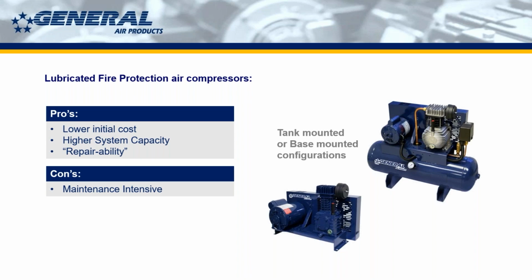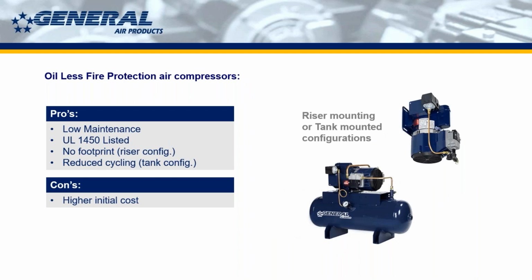And that's really the big difference. If somebody's trying to decide between oilless and lubricated, it's all about, will your customer do maintenance or not? If they will do maintenance, then maybe a lubricated unit is the way to go. If you know that's going to be a place where they don't consistently have you in, things like that, oilless is probably going to be the better way to go. But none of them are set it and forget it. Not even oilless. It's low maintenance, not no maintenance, for the oilless compressors. And that's the first bullet point there.